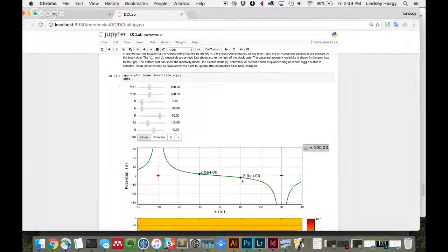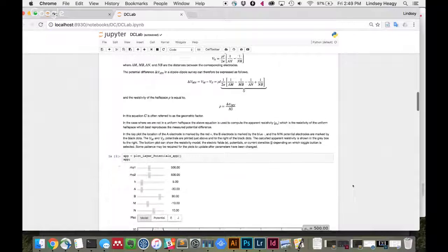So if I take this measurement here, where I take this potential difference and compute it, what that total difference voltage is, I'm just going to get some number that looks like this. So I'm going to get some number equal to rho, the resistivity, times the current, times this factor here, which is just a geometric factor. It's like 1 over the distance between the A and M electrode, M and N electrodes. So we just have these numbers here.